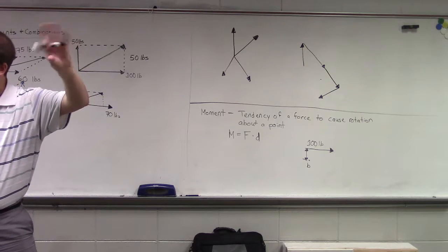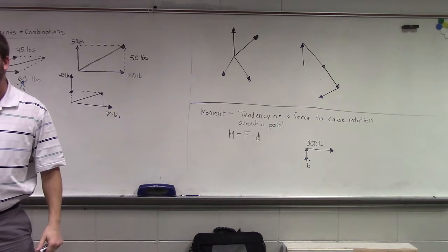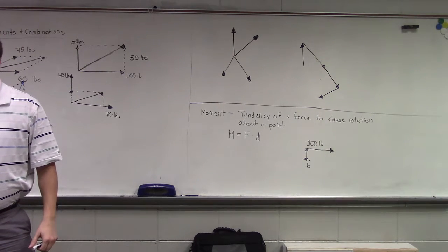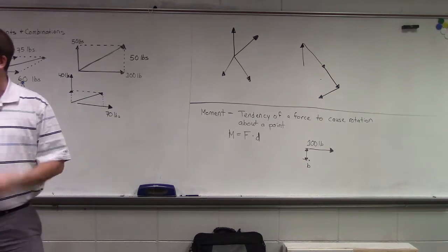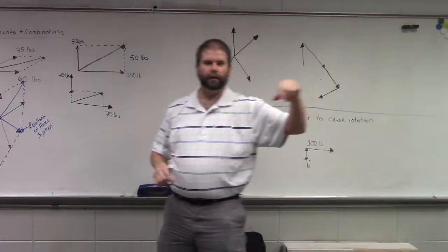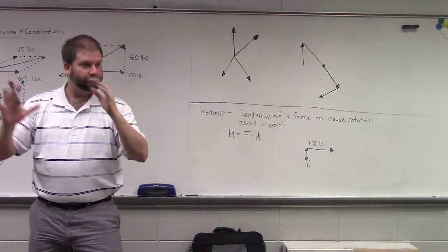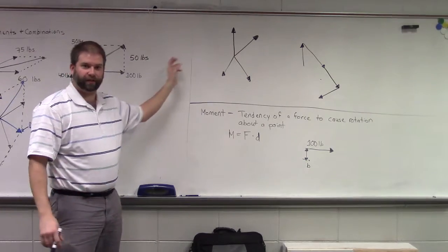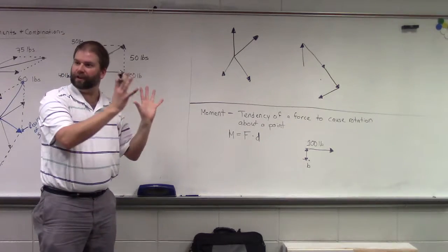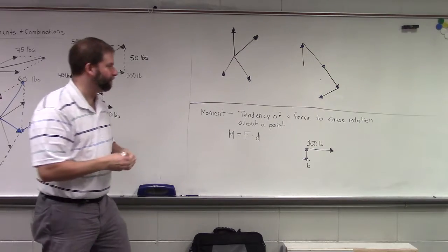We have rollers over the piers, right? We have pins along one side of the bank. Why do we do that? What happens if we pinned a bridge deck in multiple locations? As it's expanding and contracting, if we're providing resistance at a bunch of points, couldn't we crack the bridge? Right? We could involuntarily fail it.